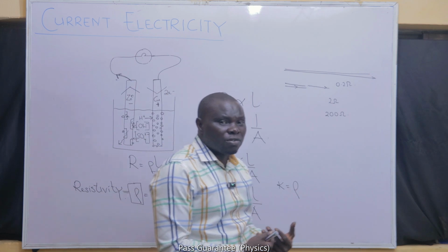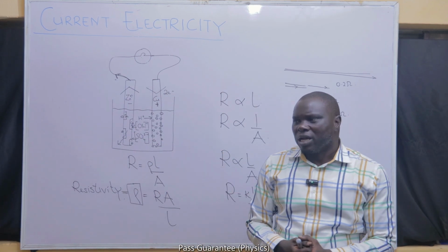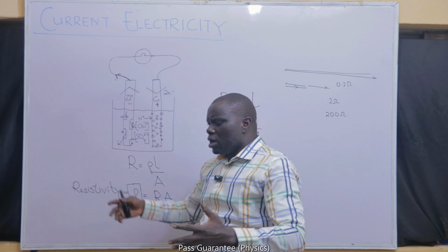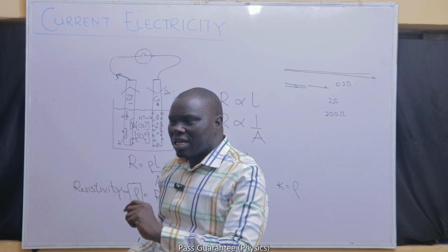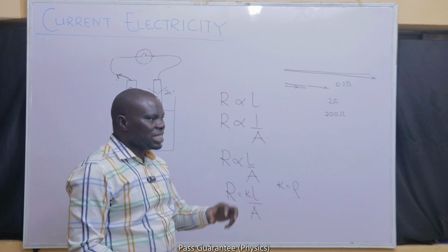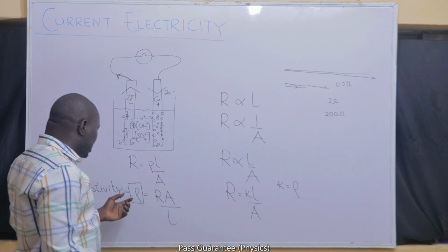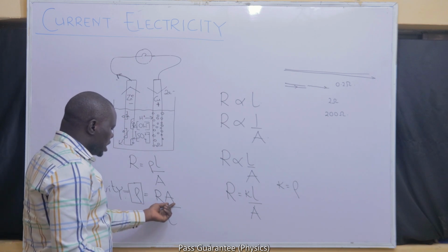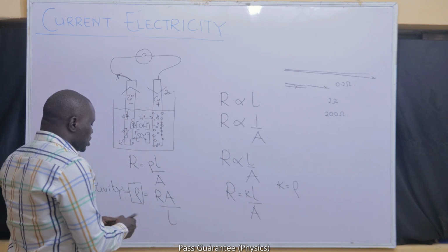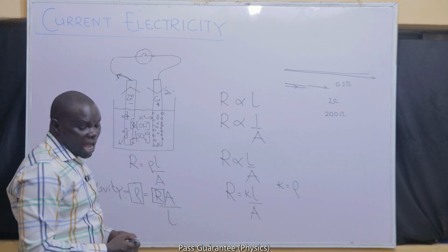It is a property of the material that does not depend on how much of the material you have. Whether you have a small amount of copper or a large amount of copper, the resistivity of copper remains the same. Once you just know the name of the substance, it has a fixed value for its resistivity. And I can now use that resistivity with the cross-sectional area and the length to cut the wire into the exact resistance that I need it to have.